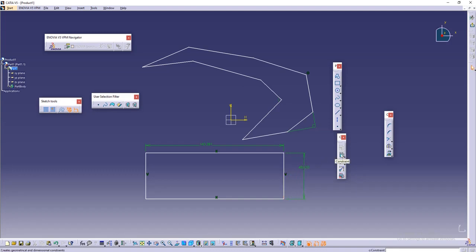So now once I clicked here, it is showing in the pink. Why? Because it shows that you are over constraining something. You have already given some dimension to this, and this is exactly the same line as the bottom, so there is no need to create the extra dimension with that. So it's showing it is over constrained, overly dimensioned. So you can just undo it with Control Z, right?